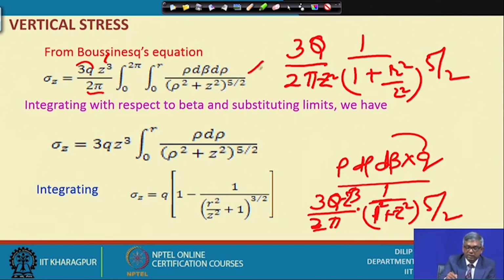Now, this is a double integration. For beta, 0 to 2 pi, ultimately it will come 2 pi. So, 3 q z cube by 2 pi gets cancelled. Then 0 to r, rho d rho by rho square plus z square to the power 5 by 2. Now, by the substitution method, rho square plus z square I can consider as a constant, and that can be further substituted and integrated, putting in the finite integral limits 0 to r, where r is the radius of the footing.